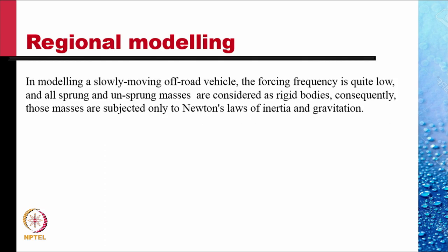Regional modeling, where the segmentation is done on space. In modeling of slow-moving off-road vehicles, the forcing frequency is quite low, and all the sprung and unsprung masses are considered as rigid bodies. Consequently, those masses are subjected only to Newton's law of inertia and gravitation.